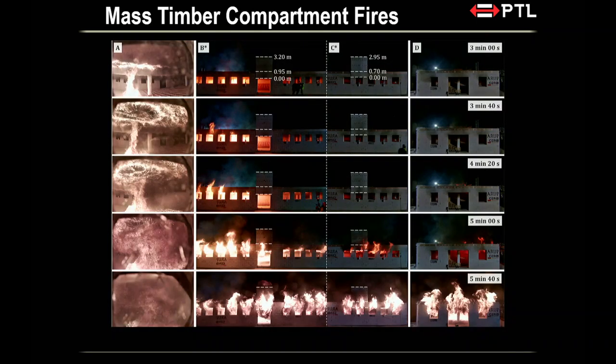Is it always assumed that all your windows are breaking from a ventilation point of view? I will also get to that in a minute. I would love to have assumed all the windows are breaking, but there will be rules and regulations that will not allow me to do that.